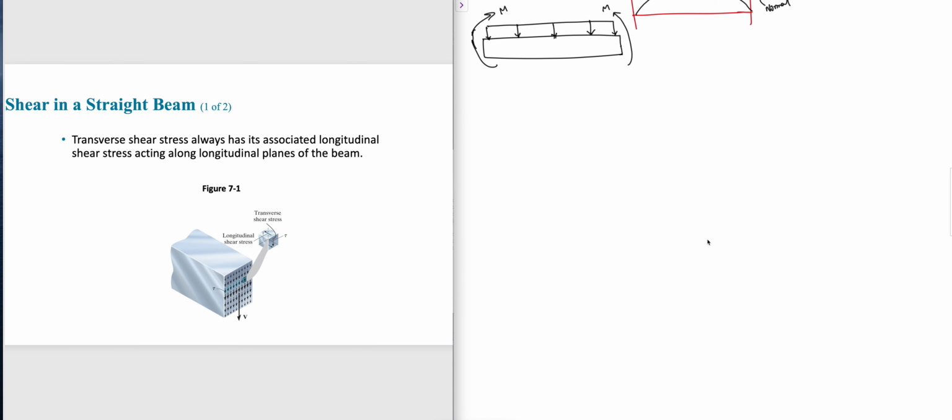Some bending moment. What I want you to do is we have to come up with the formula for V at a certain cross section. That means when we make a cut somewhere here at a certain cross section, because this cross section is a function, the length is a function of x, longitudinal is a function of x, and because let's say there is a neutral axis, that means the centroid of the cross section. From the centroid of the cross section, going up is y,